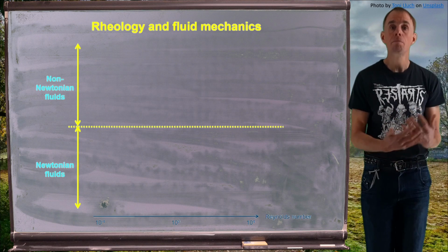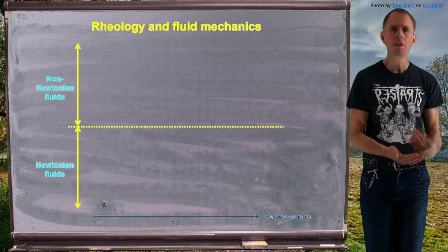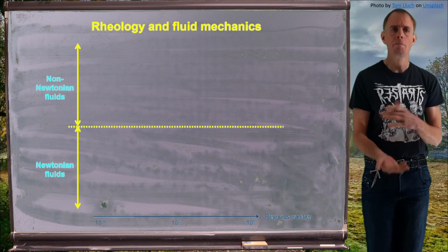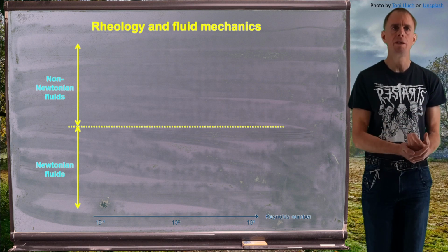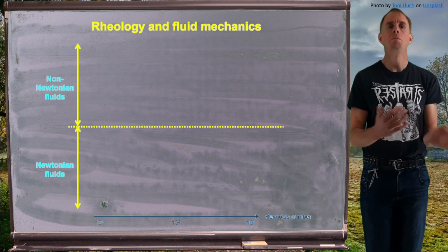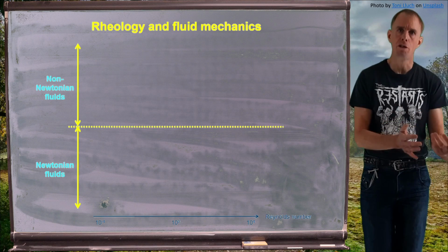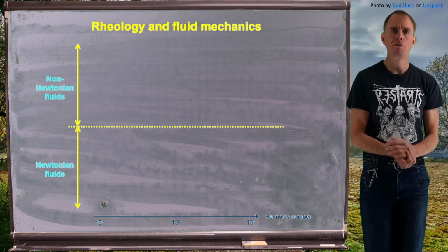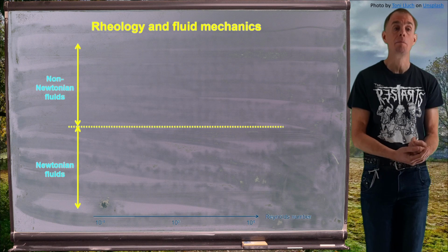Newtonian fluids are the simplest possible fluid that we can describe. Reynolds number is a measure of inertia. Basically, it separates very straightforward flow phenomena, laminar flow, from very complex flow phenomena, turbulent flow. And so nice simple fluid mechanics problems are where you have Newtonian fluids and laminar flow, and we'll be examining these in the lessons that come.